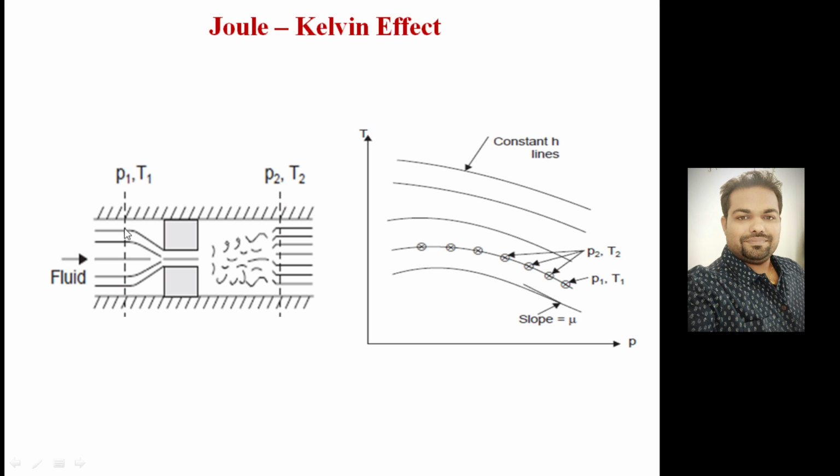container. In that, there is a very small passage through which fluid was forced to go, and finally it was expanding here. So pressure and temperature upstream and downstream are measured with the help of suitable manometers and thermometers attached at upstream and downstream locations of the flow.